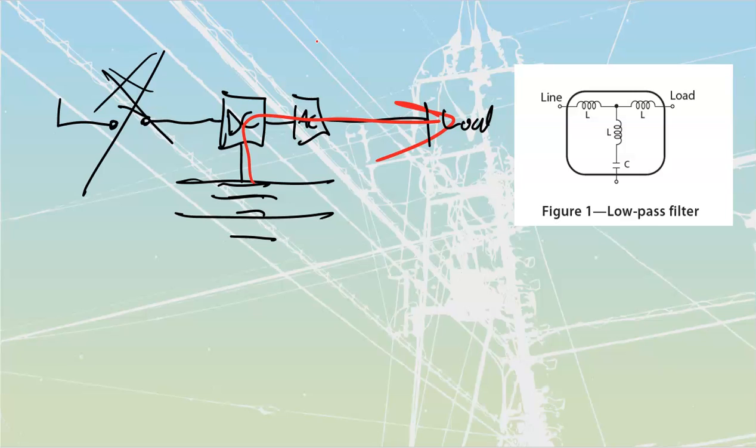They are going to be more expensive for them to be online because they are going to have continuous current carrying capabilities. They're going to have better controls. They're going to have a better inverter because it's always online, etc. And in some cases, they can actually create some poor harmonics themselves. A cheap UPS is worse than no UPS whatsoever.